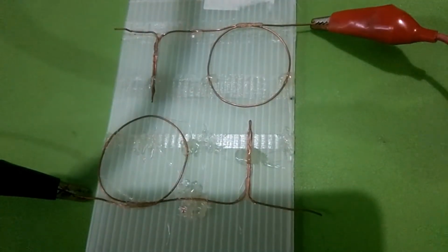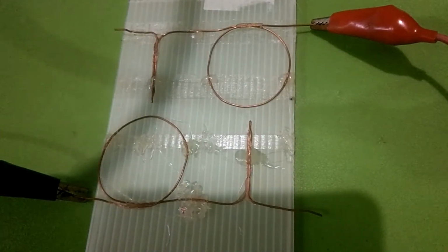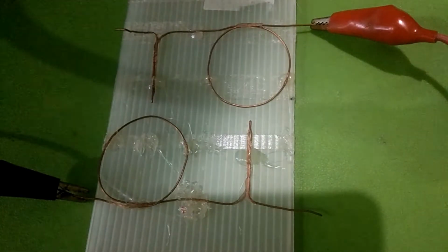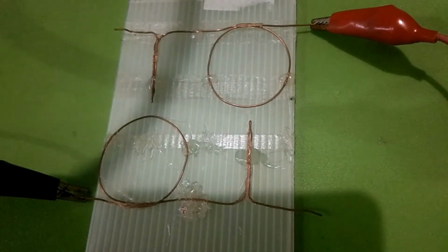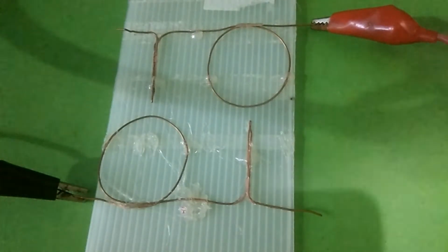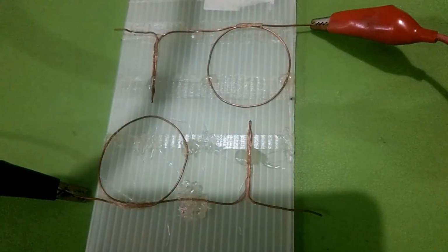The positive and negative electrodes have the same shapes, representing blunt and sharp edges, but rotated by 180 degrees. This creates two gaps with similar width between the electrodes. We want to know if the polarity and electrode shapes can determine which gap will generate spark. This time the spark occurs on the gap where positive voltage is connected to the sharp electrode.